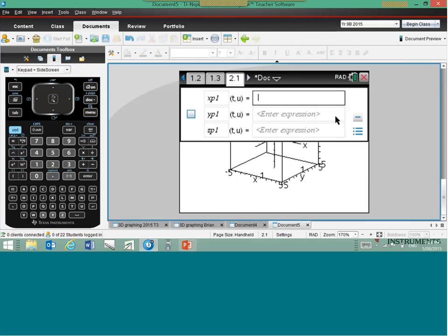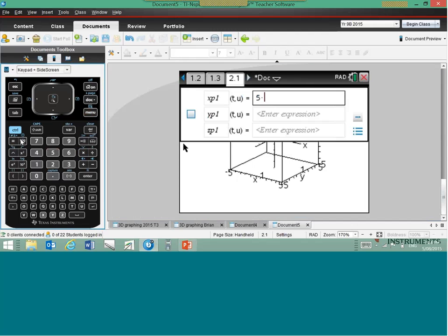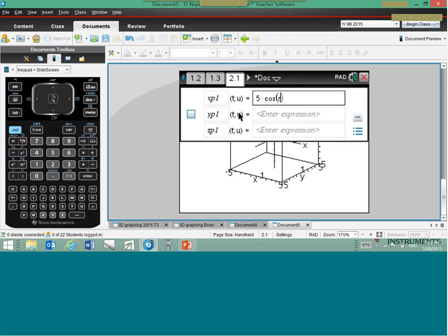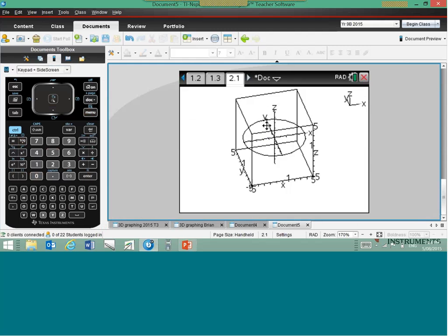So in parametric terms, I've now converted my x squared plus y squared equals 25 into the circle. If I go with r cos t, where my r is 5, by cos of t, and at this point, avoid tab and avoid enter. We're actually better off arrowing down, and 5 sine t, and because I'm liking things flat, I'm just going to go with 0 for the z, keep it simple. And so here's my flatland circle.